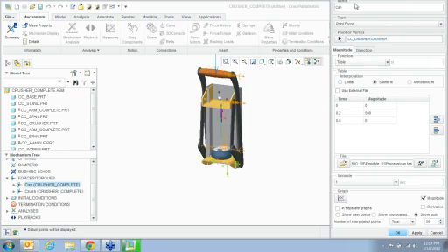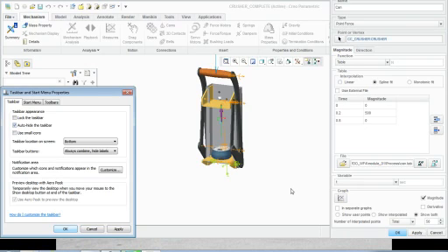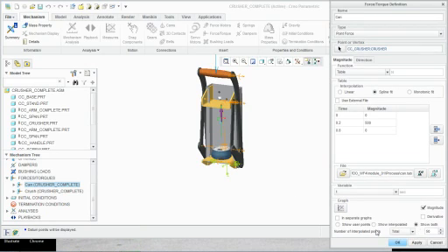And you can see we were talking about different types of fits. Let me auto hide this. So I have show user points, show interpolated points, or show both. You want to see the magnitude or the derivative of it. Now you can also do a linear fit, a spline fit, or a monotonic fit. Right? So you can do either one. All these options right here in the box when you define a force.